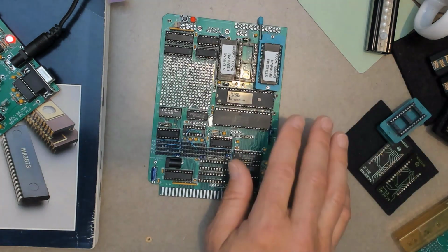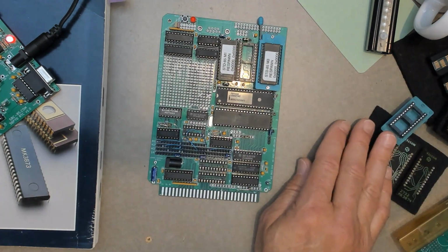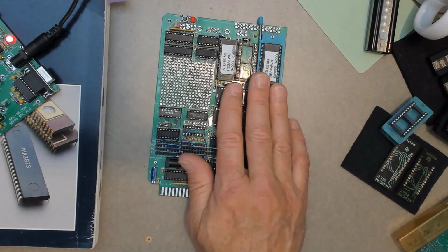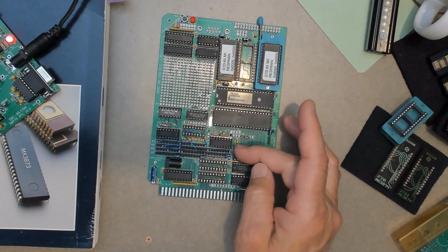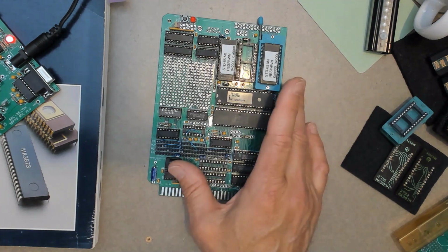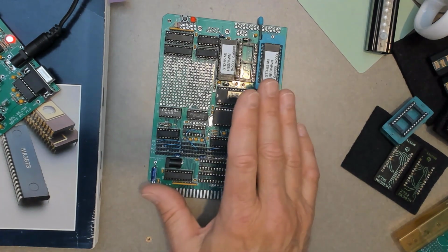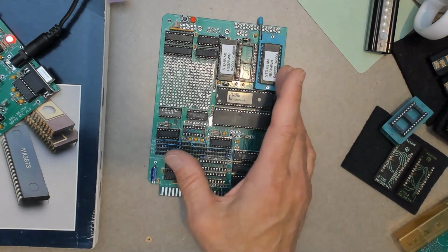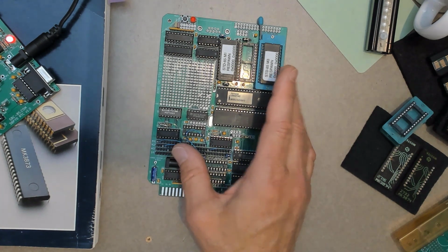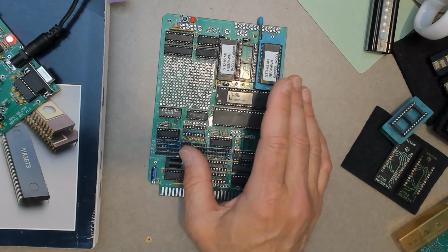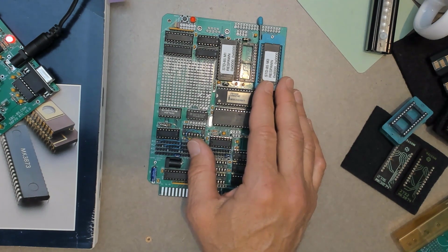By remapping memory, we're talking about changing the memory addresses of these onboard memory devices as well as the 8155 and the onboard port while a program is running on the board. So we're going to dynamically change the memory map of this board while a program is running. And in this video, we're going to talk about 4 techniques for memory remapping.